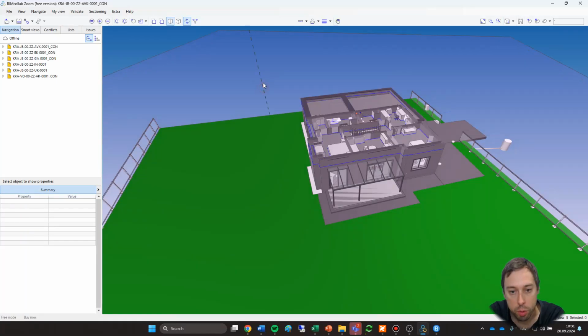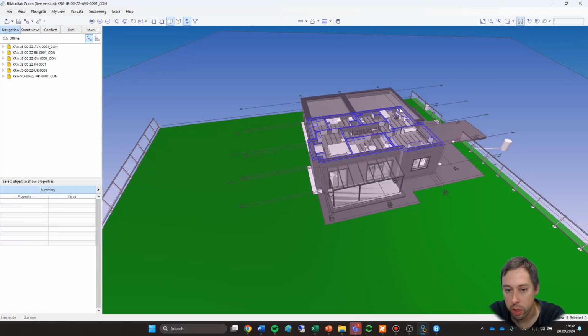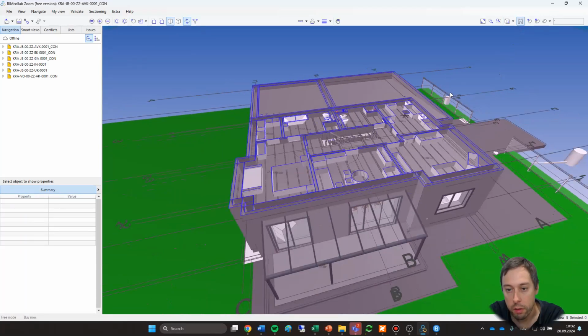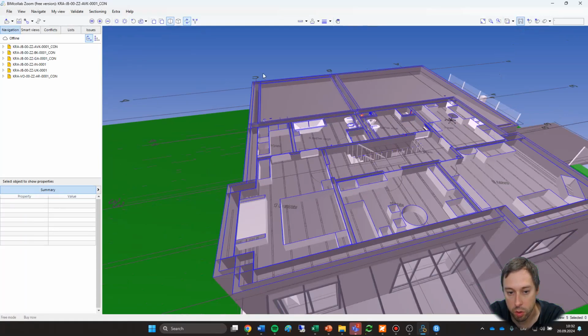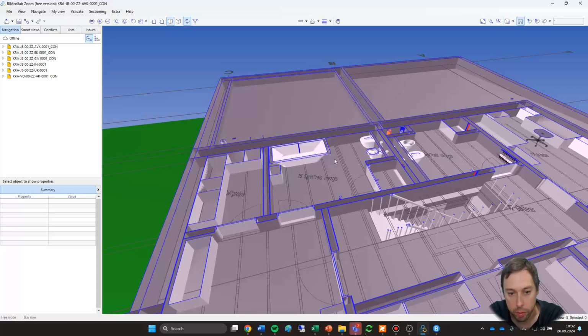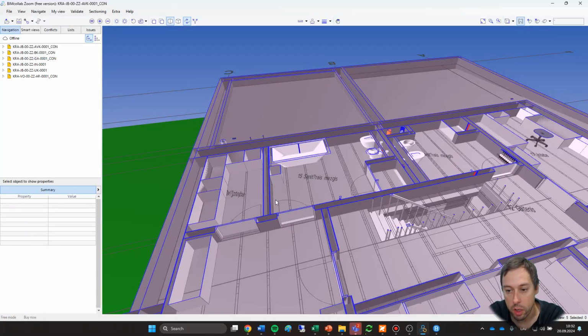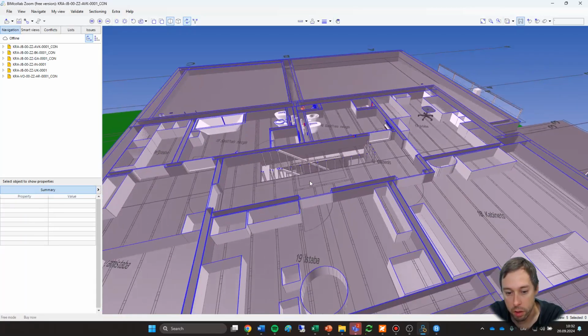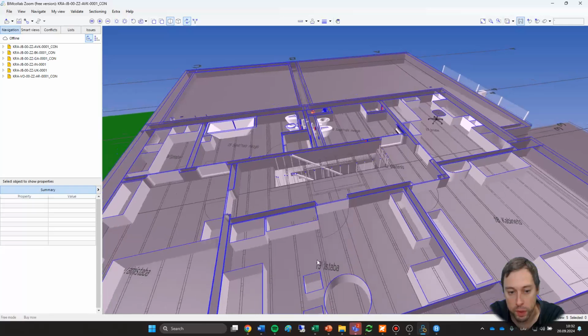One other neat tool, which I skipped, is this toggle automatic floor plans. This tool allows you to create automatic 2D floor plans based on some of the object information and also the parameters included inside. I could see that from room objects, so the boxes which represent the room, it reads the room number and room name.